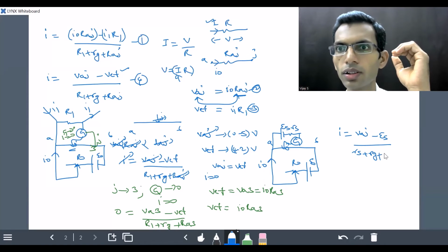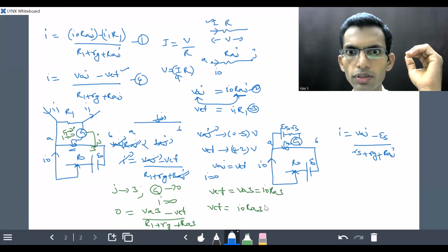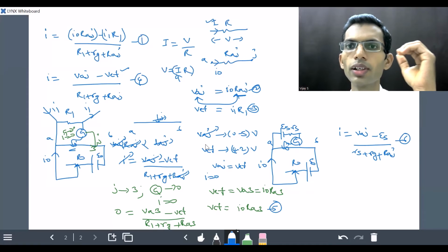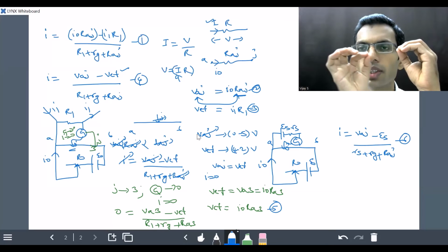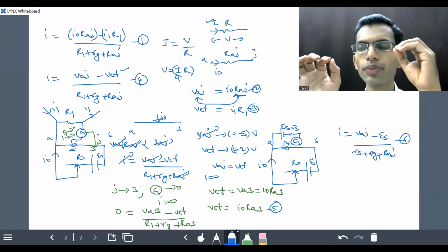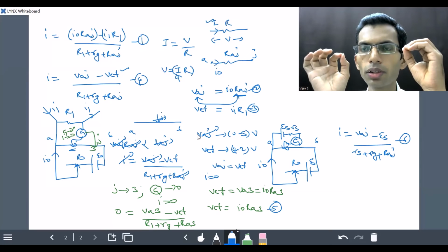So that is the thing. So this is equation 5, and this is equation 6. Repeating the experiment means what? We move the moving contact J on the wire AB and obtain the zero deflection of galvanometer for a particular position of moving contact.